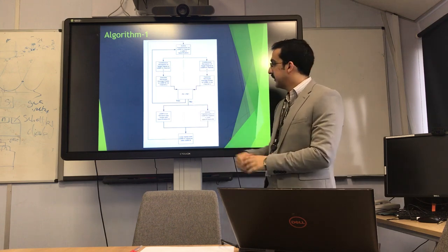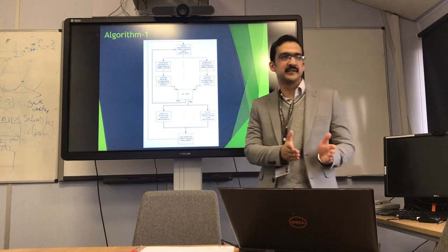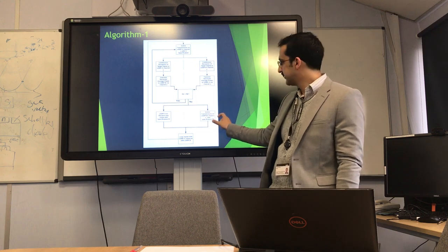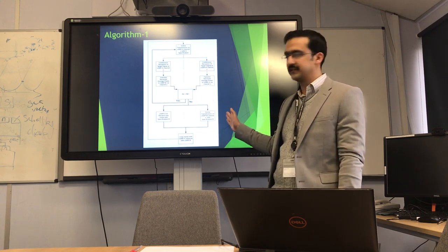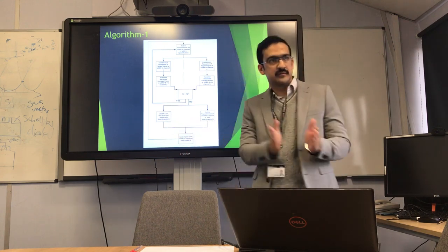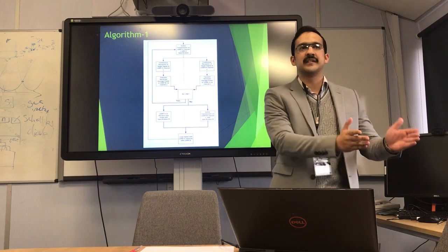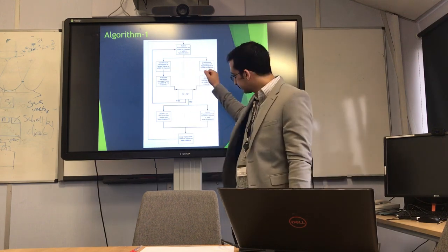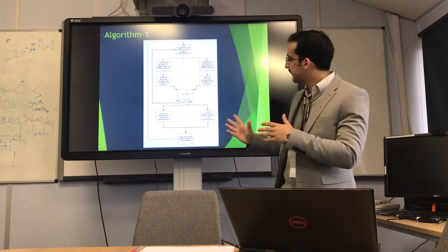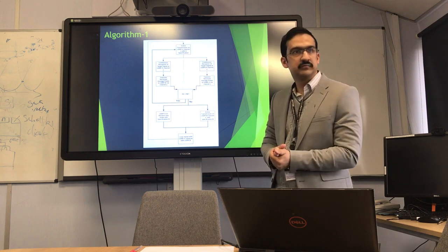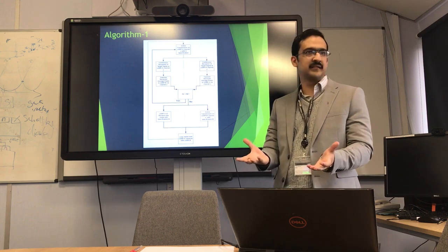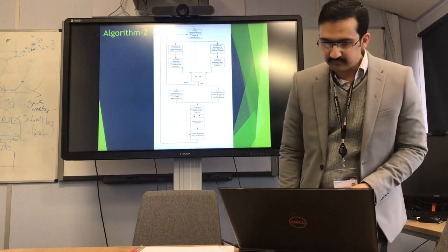Otherwise, if the power of A is not greater than the power of B, USRP A becomes a receiver and USRP B becomes a transmitter with a corresponding channel that I have named as X and Y channels with specification B, and USRP A has to convert into a receiving mode with the specification B, not A. So the loop repeats itself with USRP A replaced with USRP B. It's a very simple solution, again thanks to the flexible nature of the SDR that we can make use of.